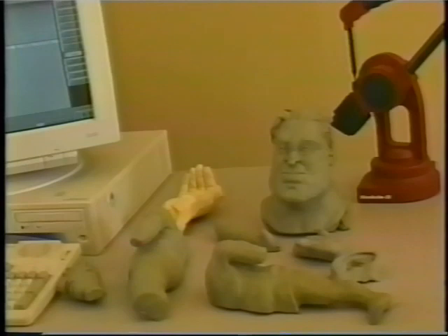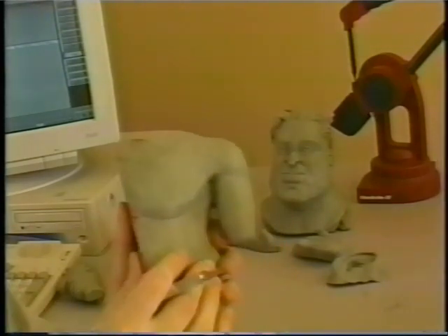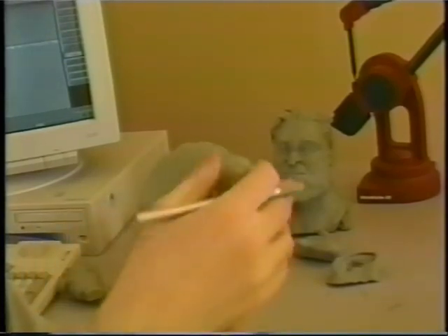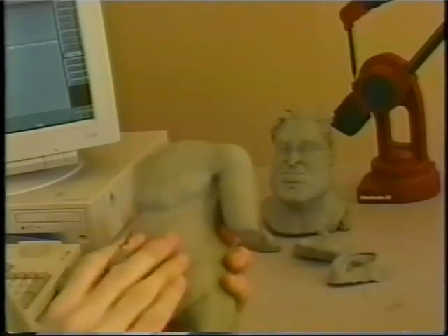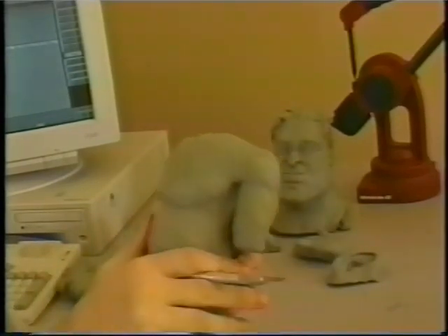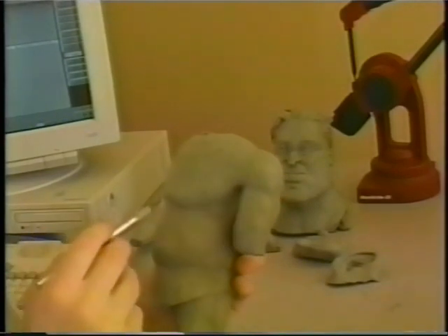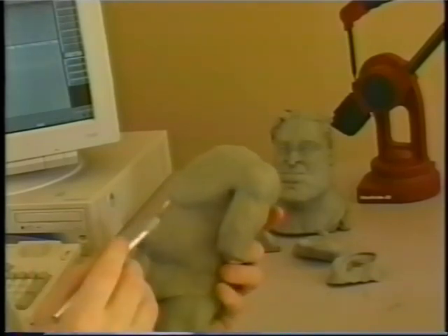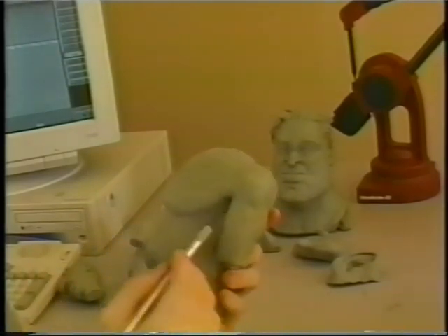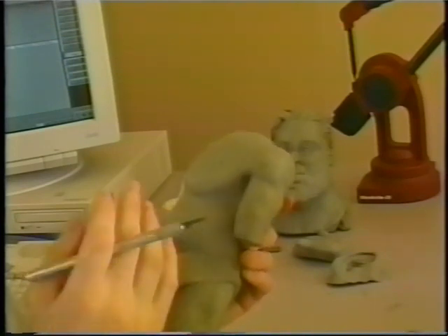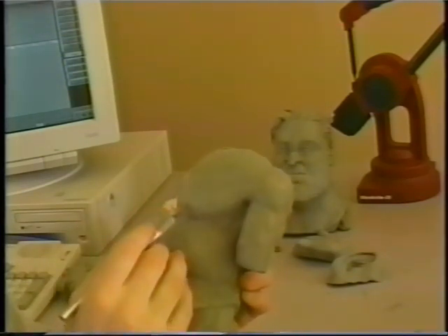Now the actual placement of the curves on the object, of the lines, is actually pretty tricky. This is maybe the minimum amount of points that you would want to use, but if we ignore this layout that I had before, and let's say the arm is going to be separate, okay? So smudge those out. Well, how few can you get away with just to make this form right here, discounting these other parts? Well, you have a curve that you want to go like that, so you definitely need one there. You definitely need one there, and one there, and one there. If you try to take out one of these curves, you're going to have a really hard time making this shape. And so what many people do in NURBS is really wind up using quite a few points.